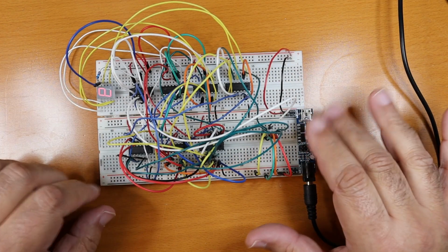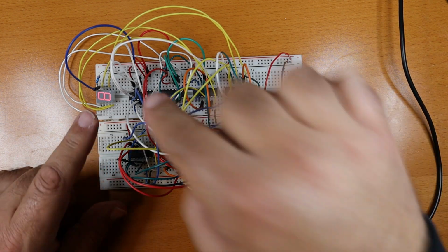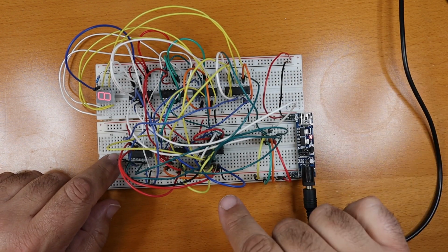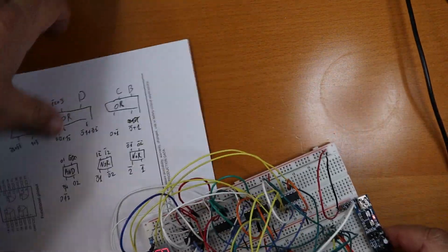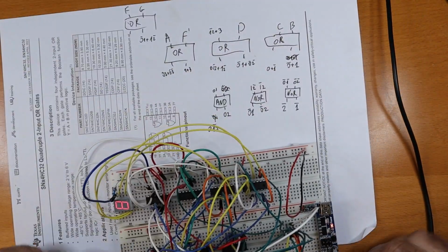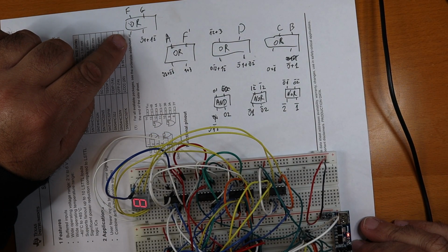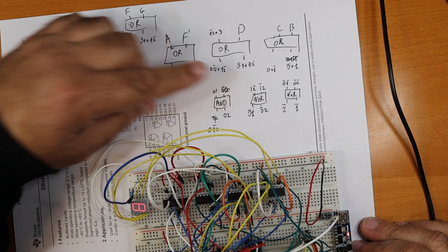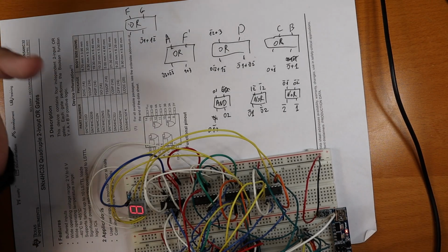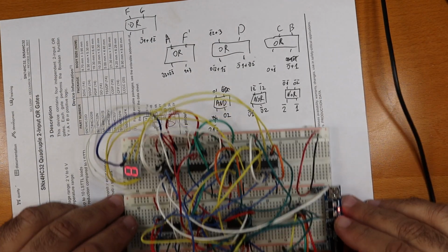So this allows me to implement a 7-segment decoder with 7 chips, which actually, if we look at the map I made when I created it, we can see that I have one OR gate that is unoccupied and one AND gate that is unoccupied. So I have, on average, half a chip that is actually available.